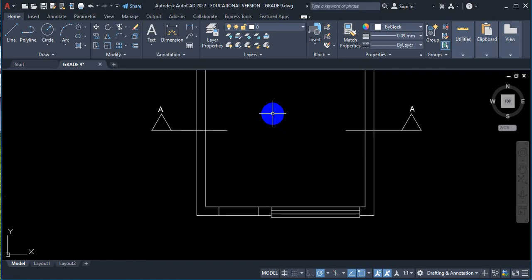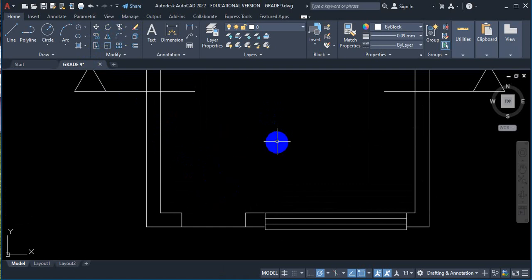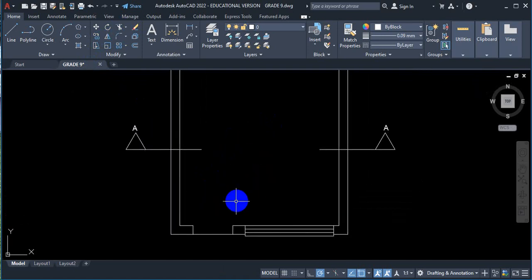Now there's nothing happening on top, but the door is right here. So if we look closely, I'm going to move this line away. What do we mean by this? We say this is the inside of the room. When we're inside the room, the floor level is the same. But once you step outside, you're stepping lower. So in other words, when you're stepping lower, it means now you have to change the direction. So that is why we have this line there, because we're saying there's a change of direction. When you step outside, you're stepping lower, but when you get inside, you're getting higher. So this here is the same level. That's why we move that line.